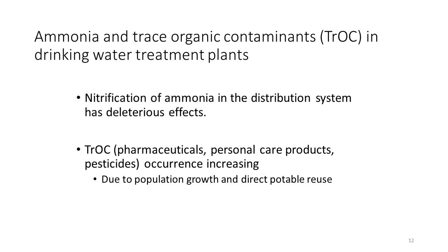Ammonia, as we all know, is a ubiquitous contaminant. By itself it's not regulated, but one of the problems that comes with ammonia is nitrification in the distribution system. Besides the fact that it can produce regulated contaminants, nitrate and nitrite, there are many other issues, including formation of nitrogenous disinfection byproducts, corrosion of copper and lead pipes, loss of disinfectant residual, growth of pathogens, and many other issues as well. So that's why we care about it.